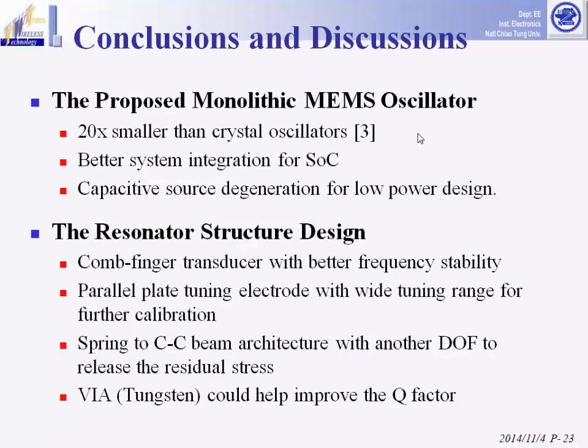This work presents a monolithic MEMS oscillator 20 times smaller than a crystal oscillator and with better system integration ability. The TIA adopts the capacitive source degeneration technique to achieve a low power design, and the proposed resonator structure was designed for frequency stability, wide frequency tuning range, and low residual stress. And we also find tungsten wire could help improve the